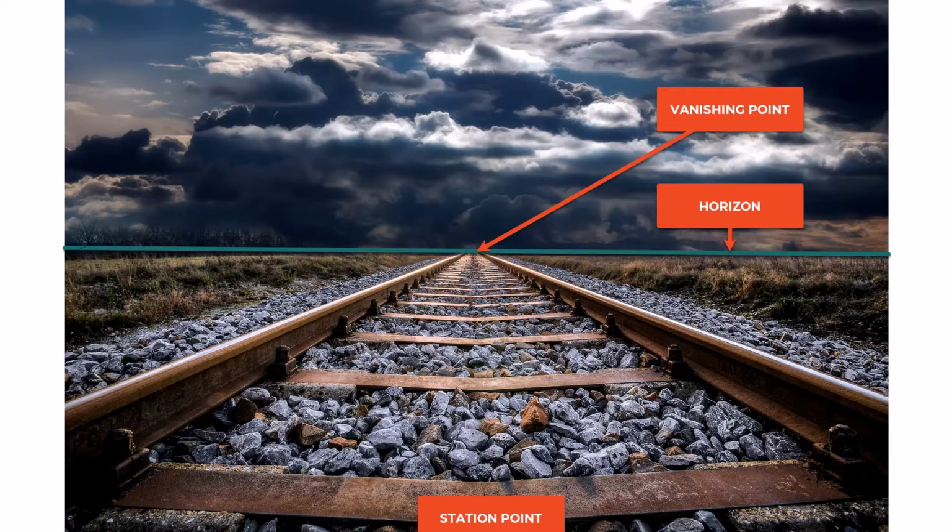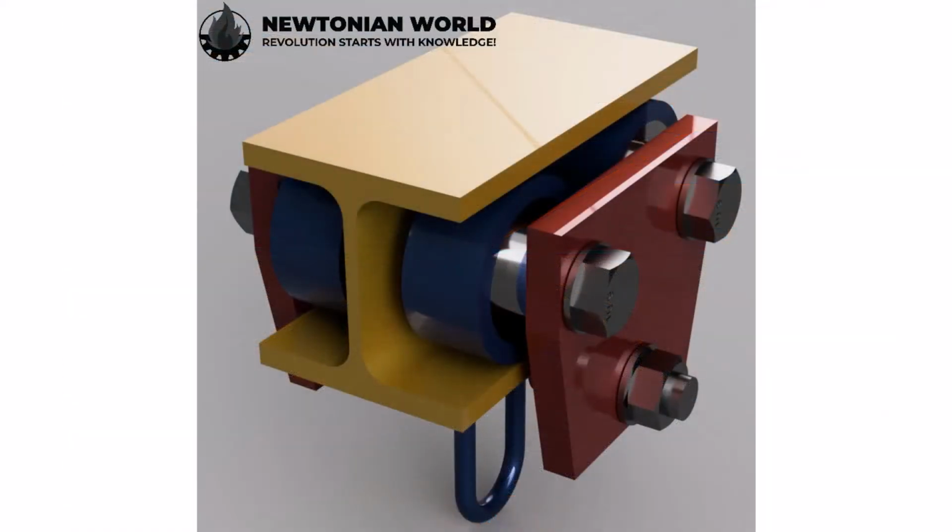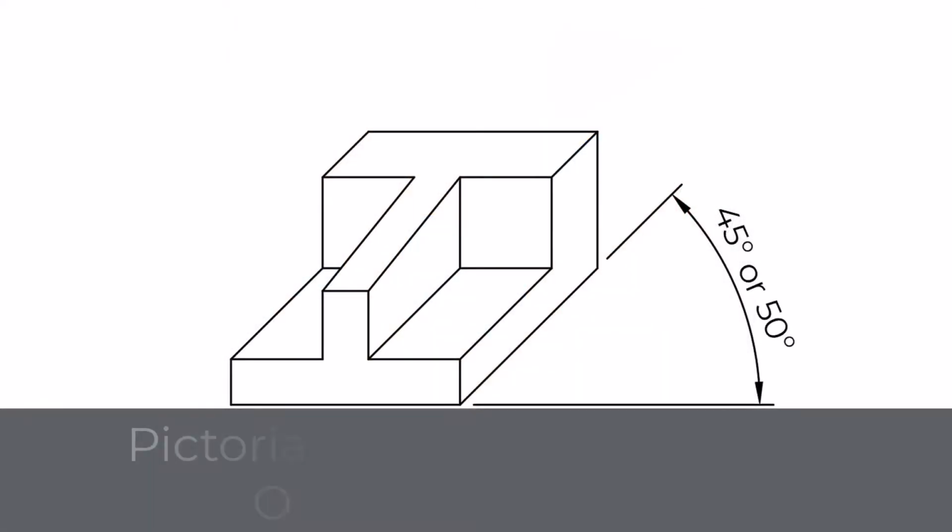The perspective projection is rarely used in engineering drawings. Even though we can easily create it with CAD software, usually, isometric projection is shown on the drawing. However, as perspective represents the true view of any object, it is handy to use it for product visualization. Sometimes, it makes sense to put things into perspective. No pun intended.